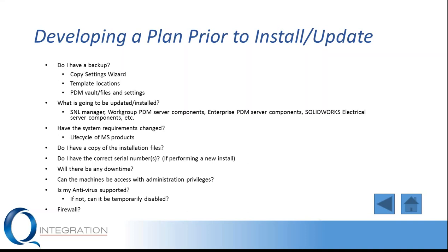Some antivirus software that is out there is not actually officially supported with SolidWorks. If that's the case and the antivirus is causing a problem with the install, we may choose to temporarily disable it if we can. And then we also want to take a look to see, are we using a firewall? And if we are, we need to ensure that the correct port numbers are open for communication with SolidWorks and the various products.